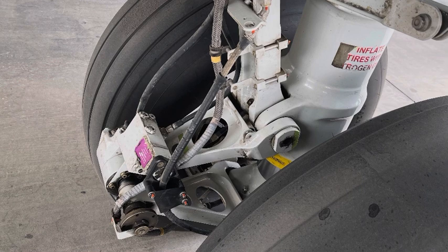Once the shimmy damper is broken down, the landing gear will be free, so the piston inside of the cylinder will be free to move. It's not going to be kept straight ahead, so that will cause the landing gear to have excess vibration, and excess vibration mostly causes the landing gear to be damaged, the linkages to be broken down, and the landing gear will collapse. So please look at the history of the Boeing 737 Classics and you can find plenty of such events.